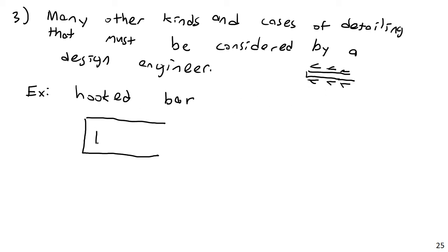Imagine if you took your rebar and curved the end of it literally into a hook like this, like a 90-degree bend. Now, if you want to pull this thing out, you're going to have to pull out a massive chunk of concrete. So this is what we refer to as a 90-degree hook. And you could also have a 180-degree hook. There's a whole bunch of details that go into how to size these, things like the minimum radius. This would be like a 180-degree hook.